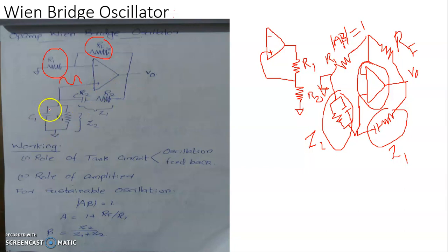However, this is an RC tank circuit. It will be associated with heat loss of energy, so that the sinusoidal oscillation produced here will be some kind of damped oscillation. To make it a regenerating oscillation, the loss of energy in the course of each and every cycle must be supplied back to it in phase with this signal.